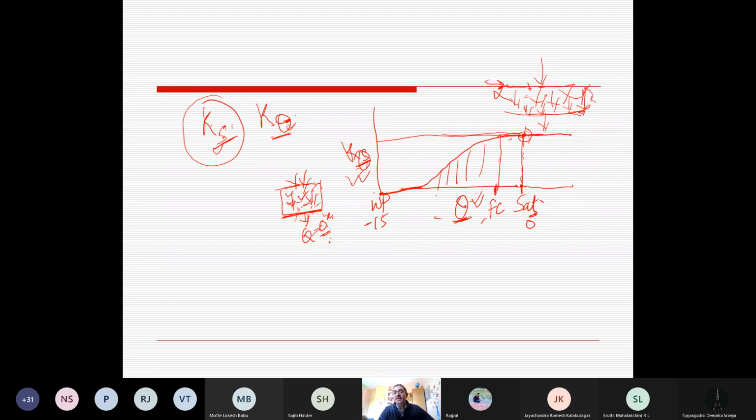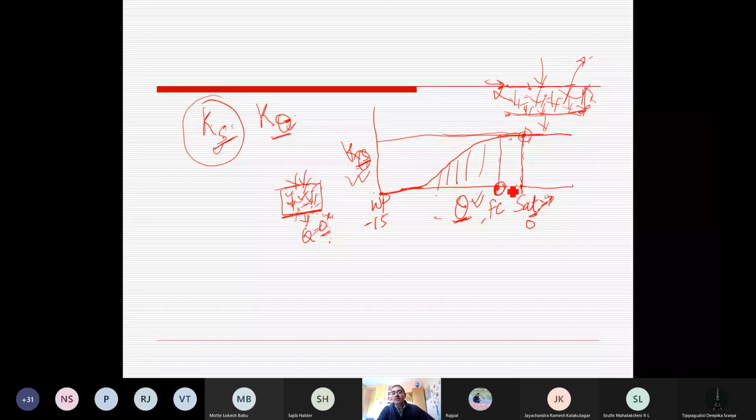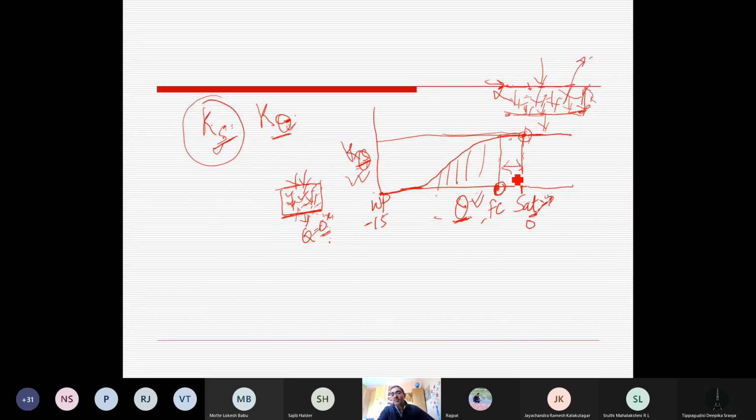So next it is important to find out the moisture content of the soil, because we are not thinking about reaching the saturation level. The reason is, in irrigation, we are interested in going up to the field capacity level, from where plants take water.